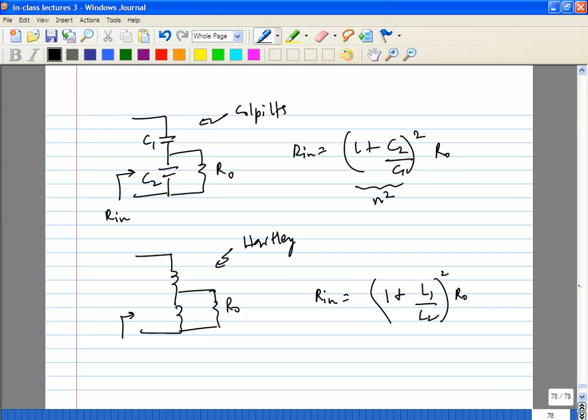So it actually has a lot of harmonics, and those pulses are aligned with the peak of the output waveform. In general that is much better for noise. You will see there are other kinds of oscillators where it's aligned with the zero crossing, the cross coupled, for example. So definitely there are trade-offs in choosing which oscillator you want to design.